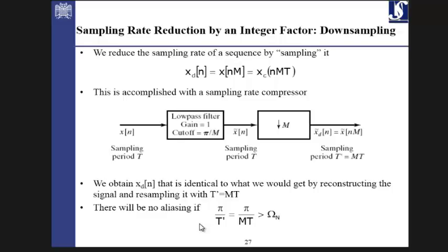And that low-pass filter cuts off the frequency pattern at pi over M, because we know that if we do the downsampling, that pi over M is expanded by the scale of M. So it means that it will reach the point of pi, which is the highest frequency. You got it? That's the reason for using this low-pass filter in the beginning and then doing the downsampling. The entire system is called decimation.